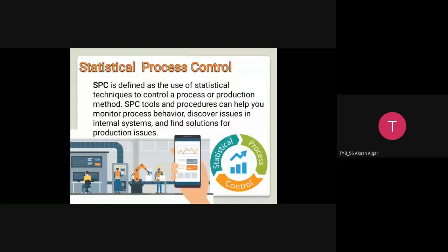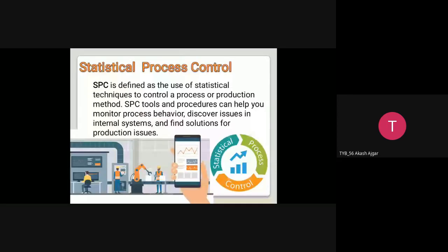Okay, so SPC means what? It is a process of monitoring and measuring variability in the performance of a process or a machine through the interpretation of statistical techniques, and it is employed to manage process quality. Simply, it is nothing but one of the quality assurance and quality tools in production for continuous improvement. We have seen the 7 quality control tools; SPC is one of the very important tools for continuous improvement in our quality process.